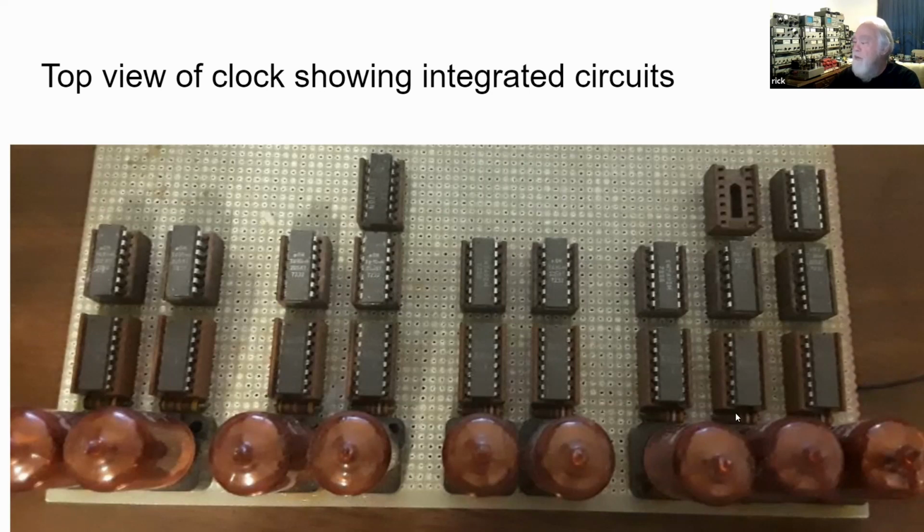And when we get to 59, we have to reset because a minute only has 60 seconds and an hour only has 60 minutes. So we do the same thing here. This chip here resets this chip to 0 when we get to 23, and it gets another pulse indicating it's 23:59.9. Then it sets this back to 0 at the end of the day and transfers a pulse to the month digits. I never added any reset circuits for the month. I just reset them manually at the end of each month.